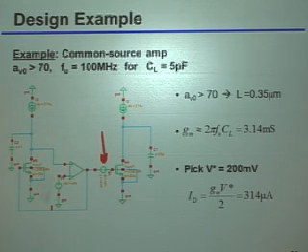Okay. So the question was, basically, where is the VDS really getting fixed? And indeed, this would be something you'd have to pick based on what you want the nominal VDS to be. Then I do my design off of that nominal VDS, or I may just sweep it across that range, again, to check that my gain is met across the range of VDS I'm trying to support.